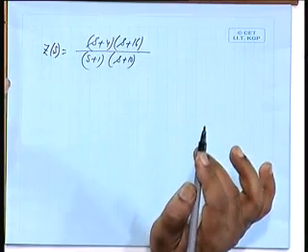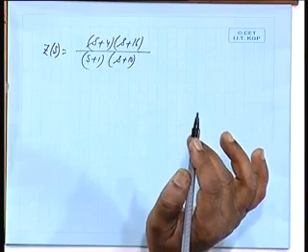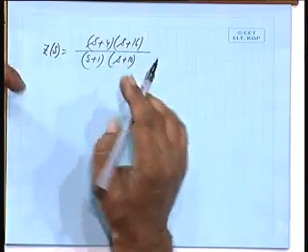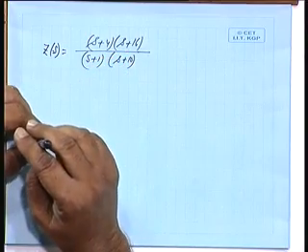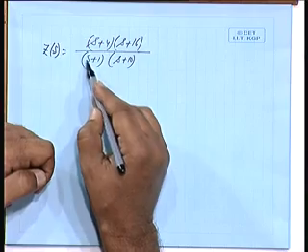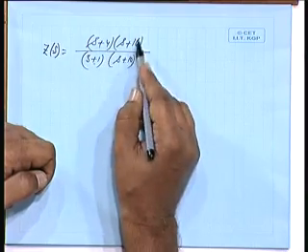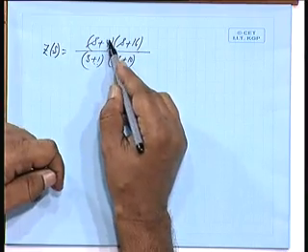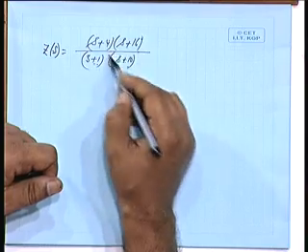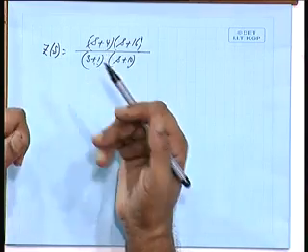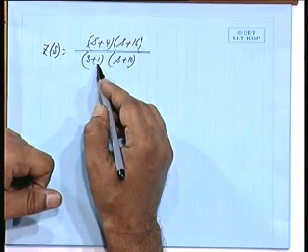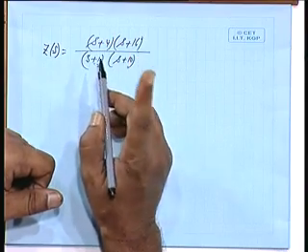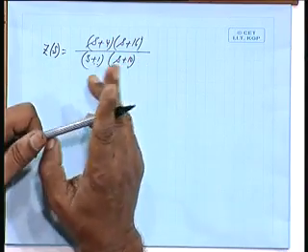Is it an RC network? It is not an LC network. Is it possible to realize this by RC elements? Poles and zeros are coming alternately, minus 1, 4, minus 10, 16. So, poles and zeros are interlaced. Okay. First one is a pole, then it will be possible to realize it by RC combination.